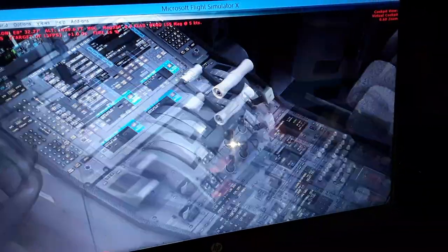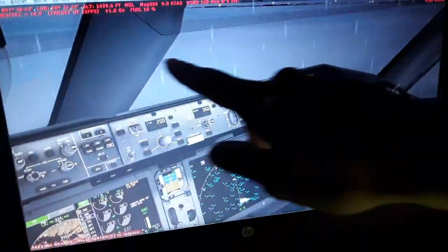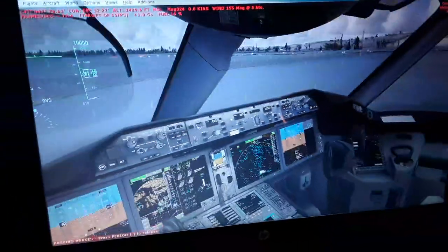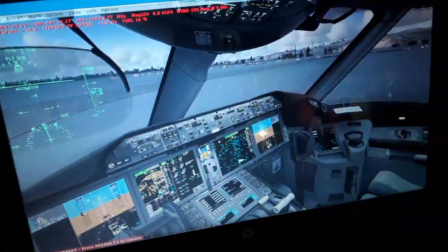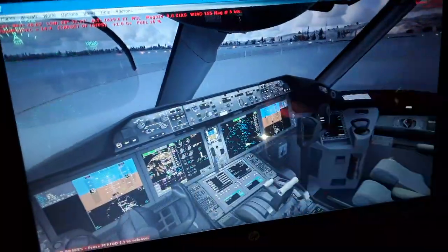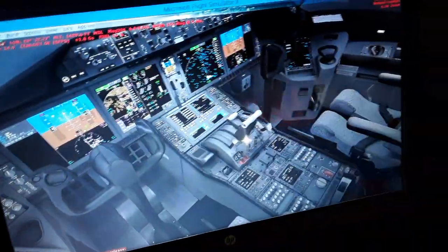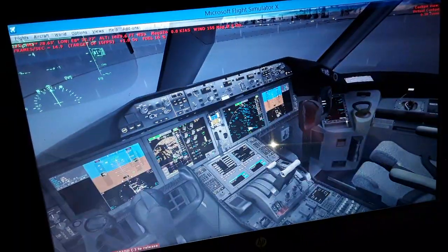We can have a failure of the L2 or R2 hydraulic systems here. We can have a malfunction of the autopilot and flight director auto trim functions, and this is an auto trim function used when we use the autopilot and the auto throttle. It trims the aircraft automatically.